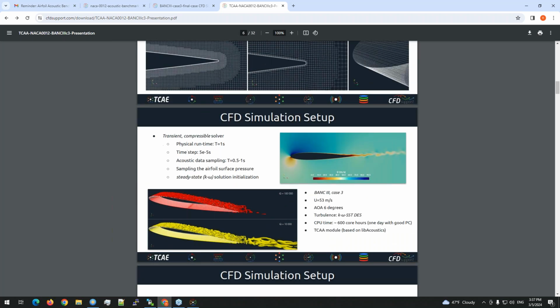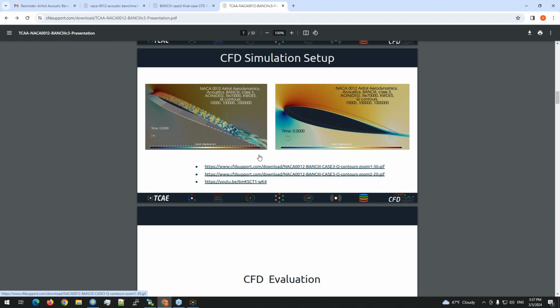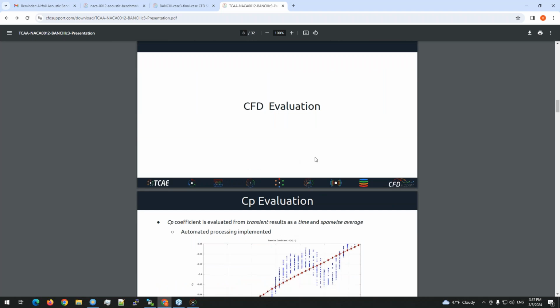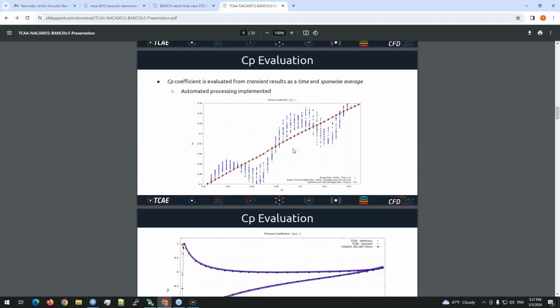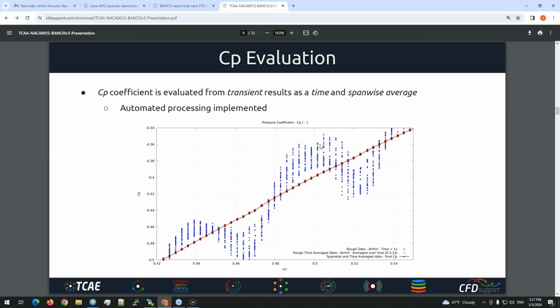All right, so all the standard CFD parameters can be evaluated and post-processed in the standard way. And what is specific for our benchmark, you can evaluate, for example, the CP, so the values on the airfoil, typical for the airfoil, like these pressure coefficients.